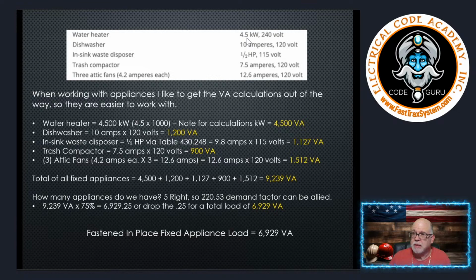All right, and we're not talking about a hot water heater that's gas that has a blower. That typically would be just a 15 amp branch circuit to a receptacle. It doesn't typically even have to be dedicated. It might be one of those receptacles that are down there for the 3 VA square foot. It might be just a general use receptacle you plug into. Got to look at the instructions from the manufacturer to see whether they call out something dedicated or not.